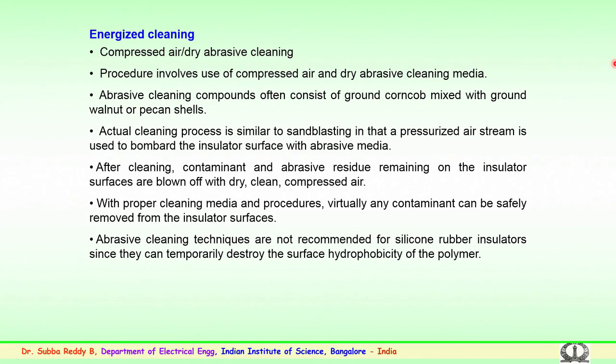After cleaning, the contaminants and the abrasive residue which remain on the surface are to be blown off with dry, clean, compressed air. These are all done during the energized condition with the supply on. So, with proper cleaning media and procedures, virtually any contaminant can be safely removed from the insulator surface.